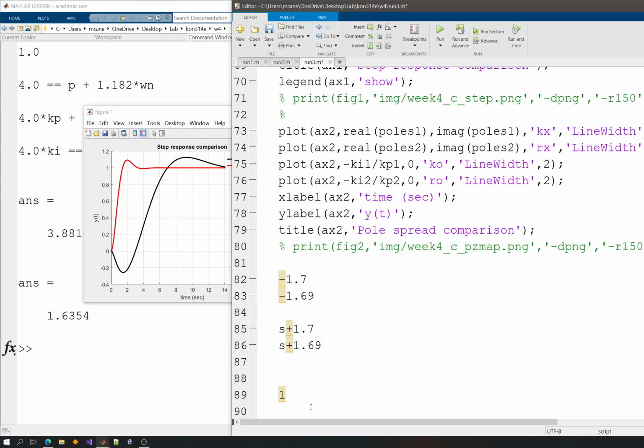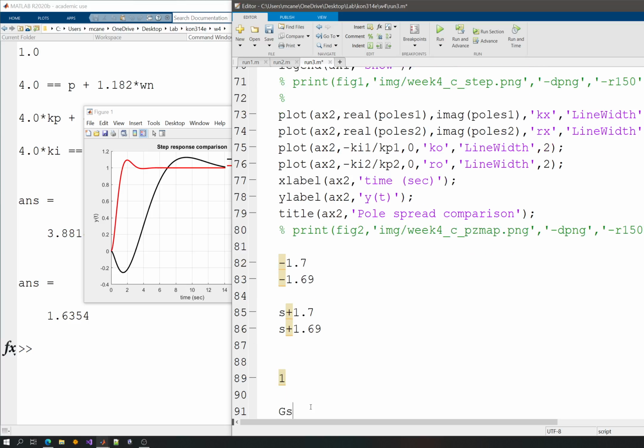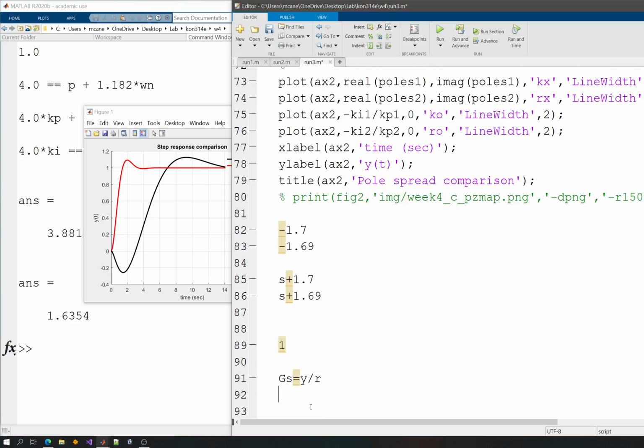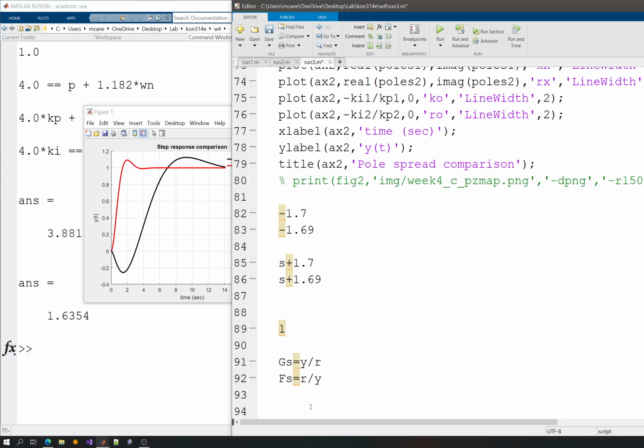Since in the steady state we are trying to have a gain of 1, if you have a system that doesn't have a transient response, and it's just ideally 1, you will have a perfect closed-loop system that tracks only the input. And this is also the reason why we sometimes design a controller as the inverse of the system. If you have a system transfer function G(s), and you design a controller that is the inverse of it, and you connect them in series or cascade, you will get the result 1.